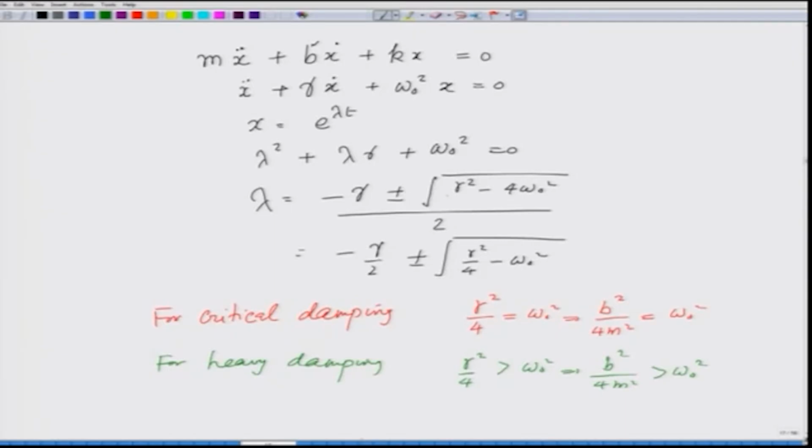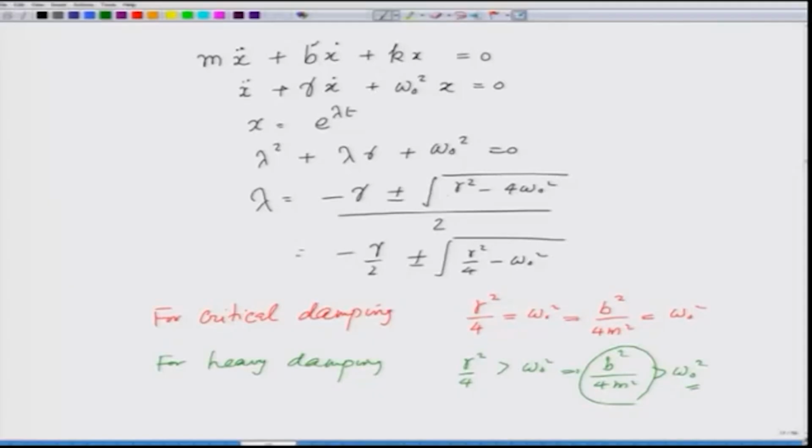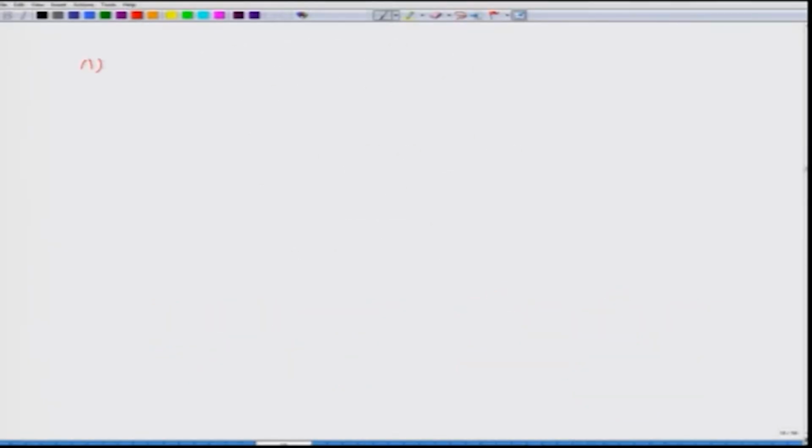Now, what we are given is that this platform is critically damped when I put 500 kilograms on this. If I decrease the mass, this gamma value will go up, and therefore, the system will become heavily damped. So, in the first case when a 500 kilogram is dropped on the platform, the motion is going to be critically damped, and in the second case most likely is going to be heavily damped. I am saying most likely because omega will also change, and that we will check. So, first case, this platform is anyway critically damped and we are dropping this 500 kg weight load on this.